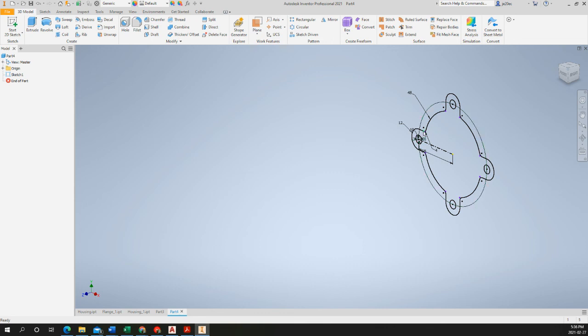I found that you should do that fillet before you do the array pattern around the circle, okay? So that's important to remember. When I did the array first and then tried to come back and do the fillet, I had issues. So changing the sequence of steps worked for me. So I would recommend that you use that same sequence.